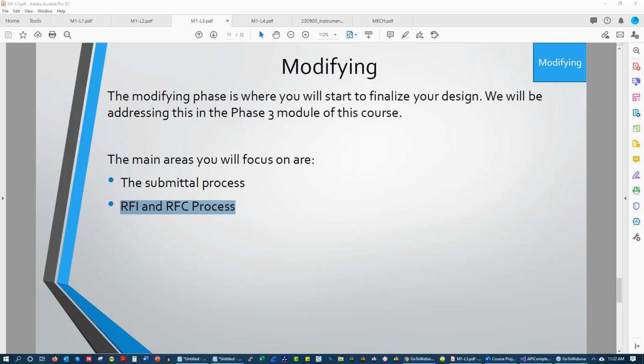If they are not providing you the mechanical drawings or the mechanical details, here's a really common one, right? You're under the mechanical. The mechanical decides that they are going to use packaged controls, like a packaged rooftop. Let's just say Trane. I'm not picking on Trane, but they're top of mind because they just went through some rebranding. So they pick a Trane unit, and you need to know what sequence of operations that Trane unit can do to make sure it's adherent to the spec. Now, granted, it should be the mechanical adhering to that because they decided to get the embedded controls, but you're the controls contractor and crap rolls downhill, so you want to be cognizant of that.